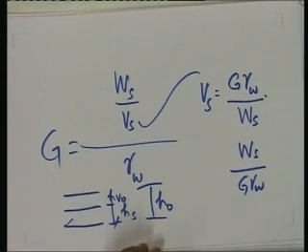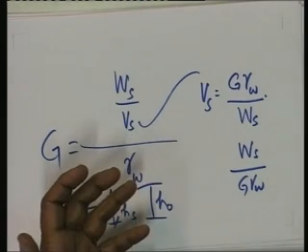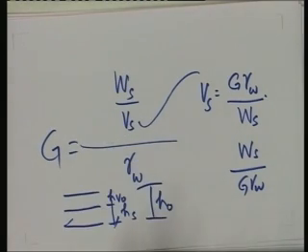Once we know this, we can calculate the void ratio as height of voids by height of solids. So, the attempt in this method is to determine the change in height of the specimen and relate it to the change in volume of the voids. So, e is taken rather as height of voids by height of solids than volume of voids by volume of solids.